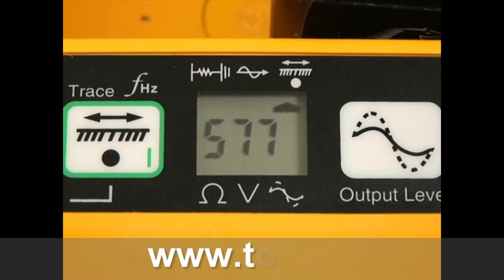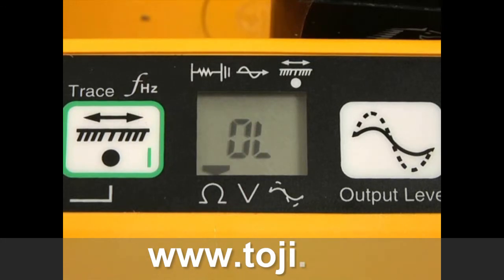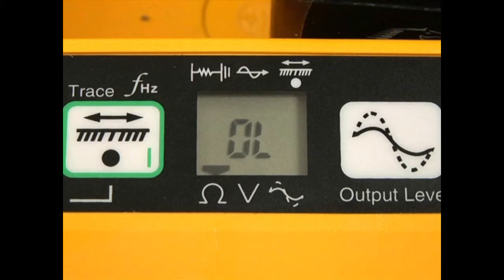facilities. If the resistance of the signal path is greater than 10K, or if the ohm meter displays OL, this could be an indication of an open line or that the return path through the ground is very marginal or non-existent. You should attempt to improve the condition of the signal path. Refer to the section Advanced Application Techniques for suggestions on how to improve your ground.